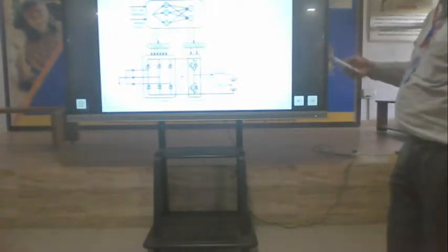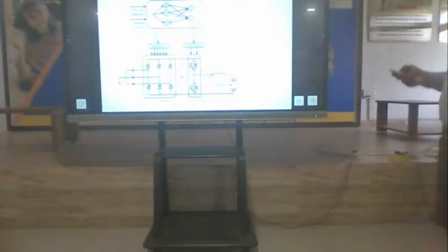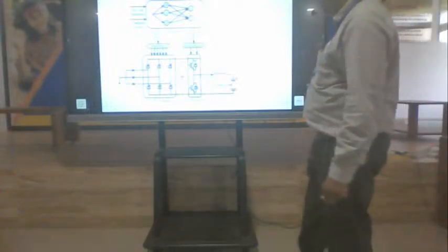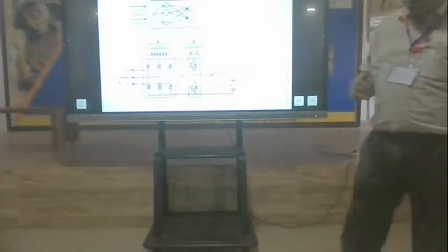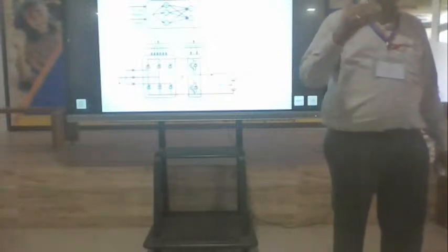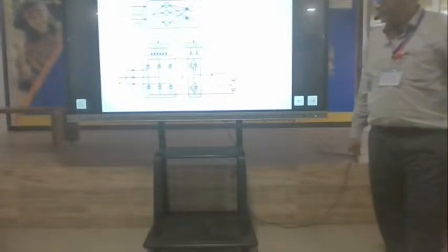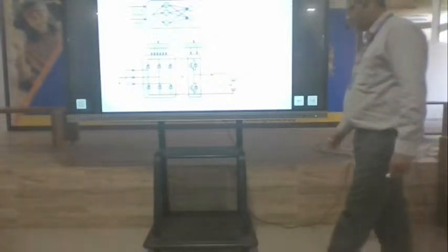Such a system will be useful for representing the controller and identification. If you take an electrical vehicle system, you will have AC/DC and DC/DC converters, because your motor is an AC motor, like a PMSM or a three-phase induction motor, but the storage battery is DC. So there should be a proper converter design between the battery and the motor. First of all, you will have the DC-DC converter on the battery side, and you have to use a bidirectional converter.